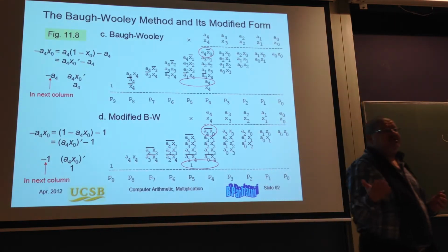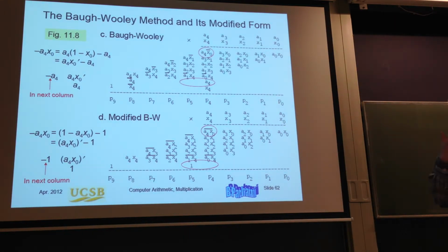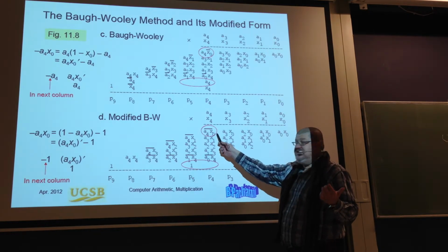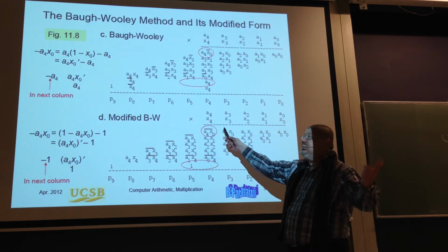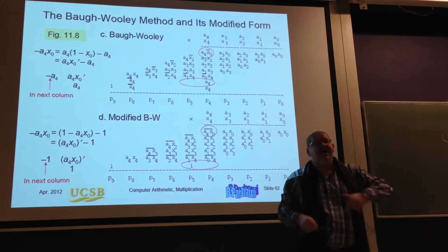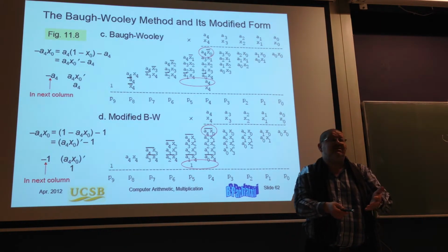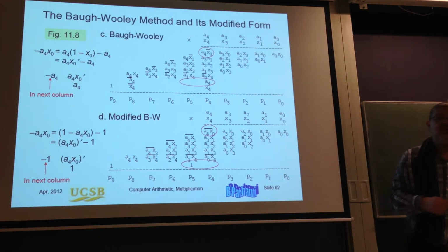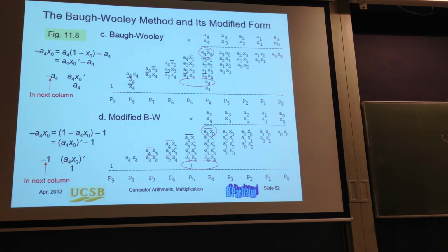Then there are 2 aspects in here. One is the effort that I put in order to do the rewriting and how I compute those additional terms. And in here I see I can compute it directly with an AND gate, while there I will need an inverter and then an AND gate, which in CMOS is equivalent with having, you know, an AND and after that an inverter.